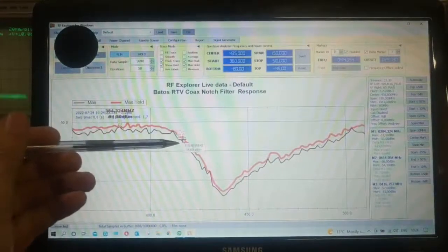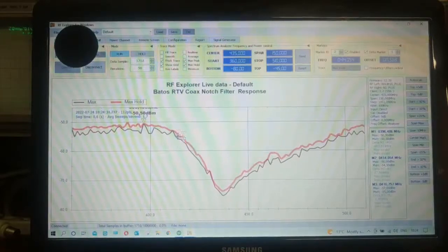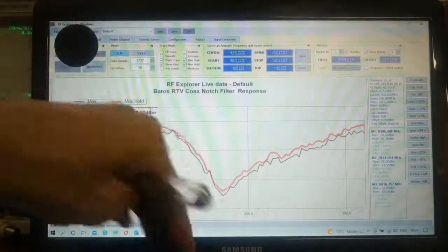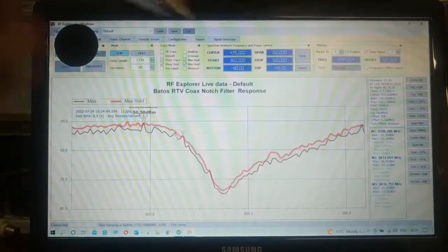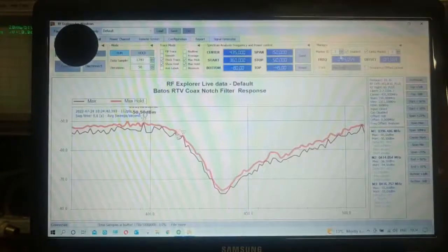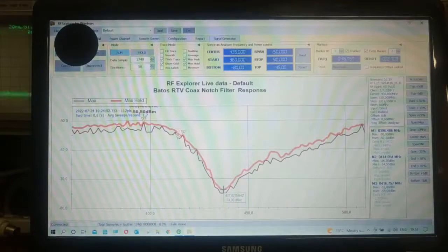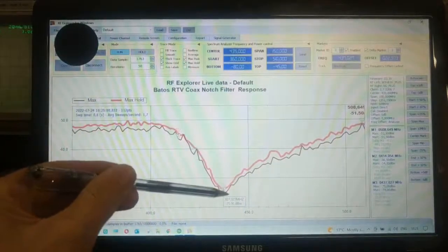dBm. So I'm just going to put the marker at 56, 55, somewhere in the 54, 50. So that's where my second marker is, which is minus 3 dB. That's where the filter actually starts attenuating slowly. And then, of course, we've got the third marker that I'm going to enable at the desired actual frequency, which is, let's use this one here, the smallest peak, sort of, and that is my center frequency of the notch filter, which is 437.